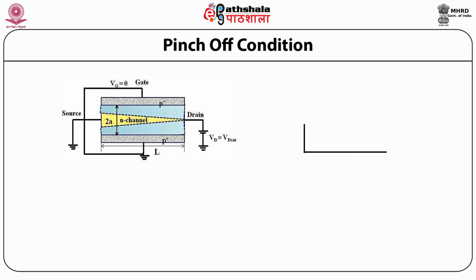At a particular value of VGS, the depletion region widens through to the P region on the other side, cutting off the channel. The voltage at which it occurs is called the pinch-off voltage Vp for a particular device, and at this value no current flows through the channel even if the drain source voltage is applied. Vp is difficult to control in production, so it varies between the devices.